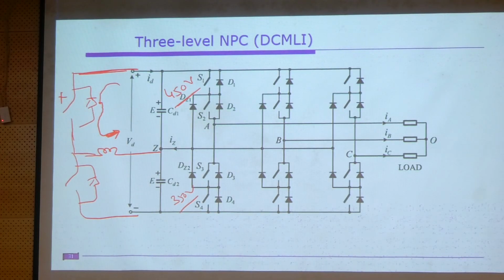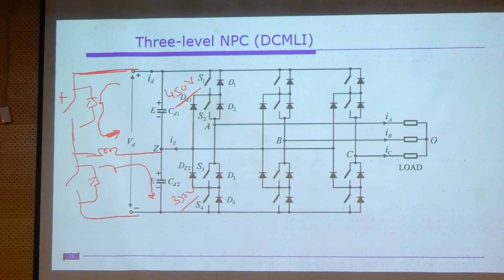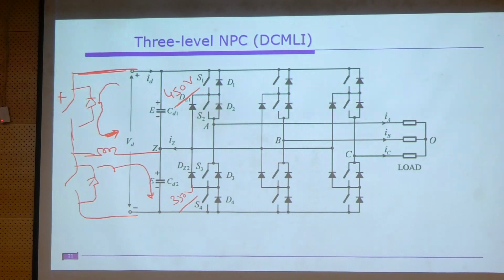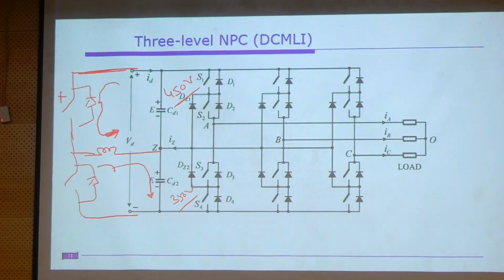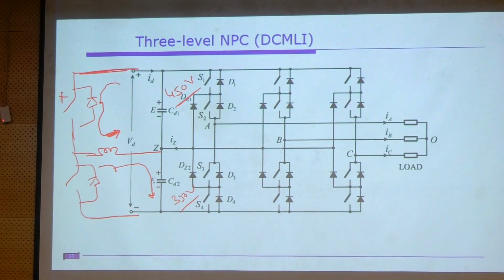You know that the inductor current will not allow a sudden change in the current direction. So now the inductor current will flow in the same direction, but through this capacitor. Now the capacitor voltage is recovered. So whatever the excess charge in the first capacitor is transferred to the inductor, and again it is transferred back to the other capacitor. Understood?